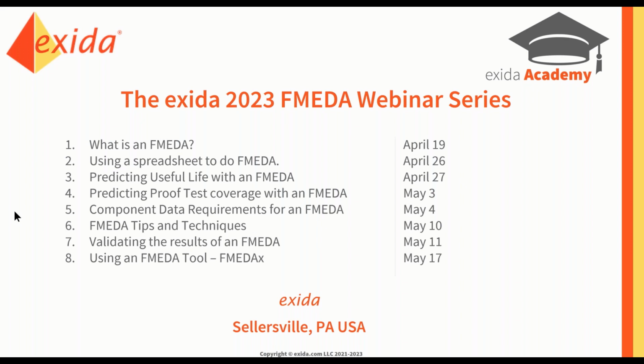There's another. What's the difference between useful life and mission time? Oh, that's a good question. It's very confusing. Mission time is how long you're planning on operating a plant or an industrial process. It's the period of time for which we do PFD calculations. Now, useful life is really a completely different variable.